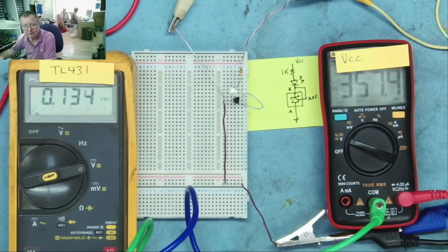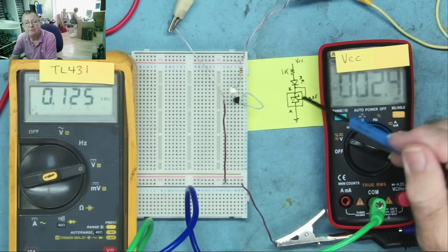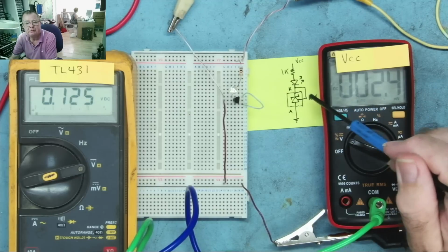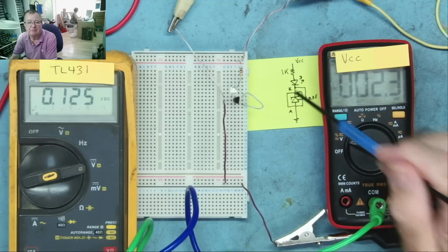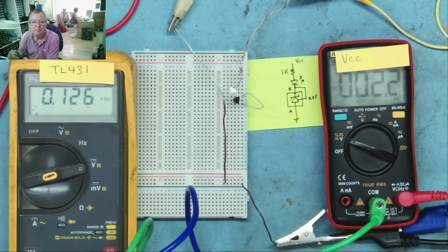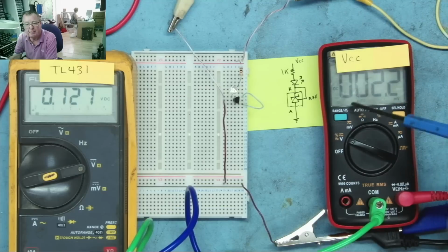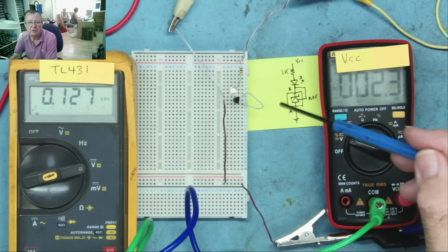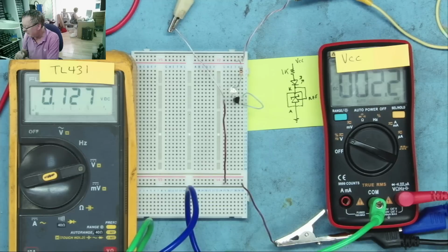Okay, I've connected up my power supply again, set the output to 0. We now have the little circuit that we see here. So this is basically the same thing. I've just substituted the Zener diode with the TL431 and I've connected the reference to the cathode. So this is now a 2.5 volt Zener, which means that when the voltage on the power input goes above 2.5 plus the forward voltage drop of that, which is about another 1.5, 1.8, it will light up.